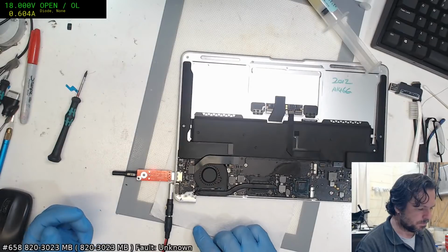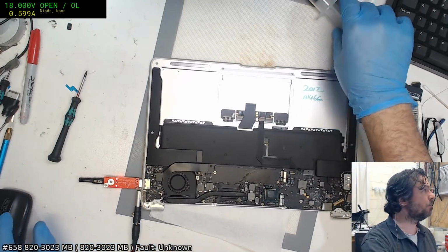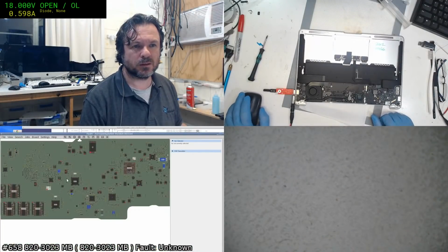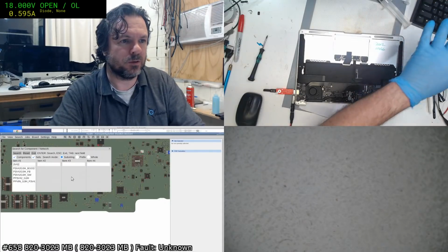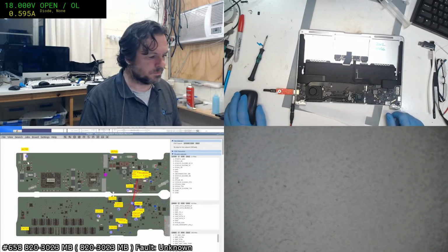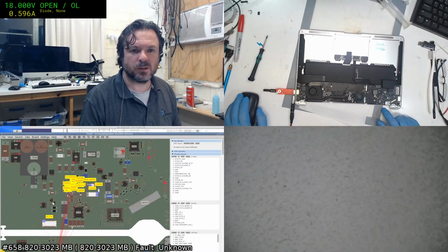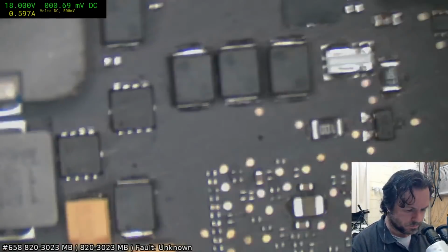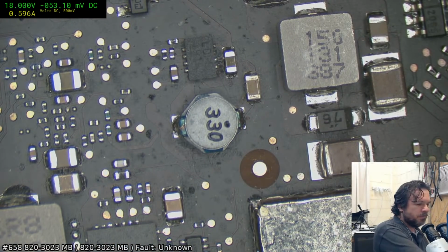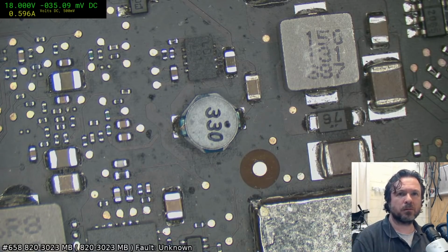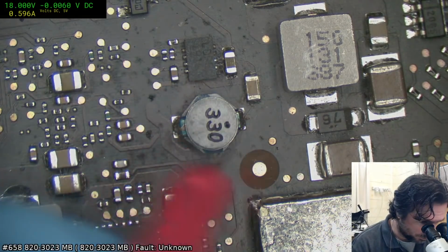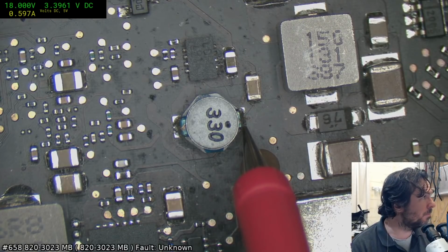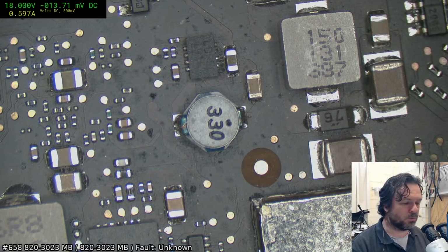Okay, so here we go. Still no fan spin. Alright. Time to check some voltages, and we've still got 600 milliamp being sucked up. So, quad view. So do we have 342? You've got 340. That is actually a smidge on the low side. Now, some... 339. It actually is a little lower than what it should be.